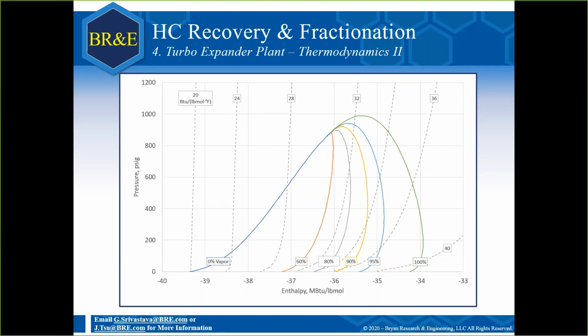Over here, you will notice the lines now change. I'm now talking about along these lines, they're all isentropic, which means same entropy. The reason why that's important, if you recall, we talked a bit about isentropic efficiency. So let's do it again with another example.